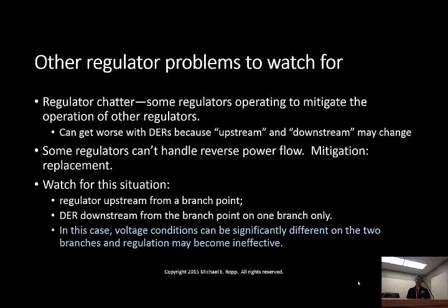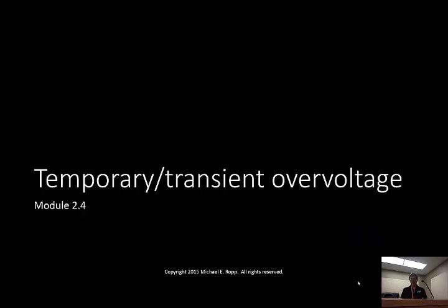So the main mitigation strategy for a case where a voltage regulator is being impacted by the voltage modulation of a PV plant is to operate off of unity power factor absorbing VARs. Ultimately, we want to look at volt-VAR controls as the long-term solution that's going to provide more benefit to enable the PV to help flatten the voltage profile of the feeder.